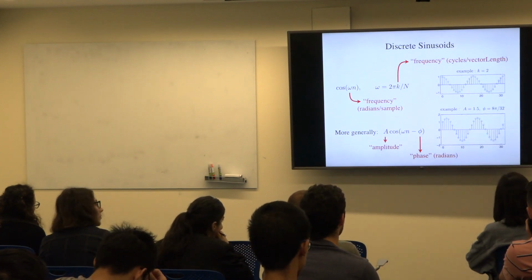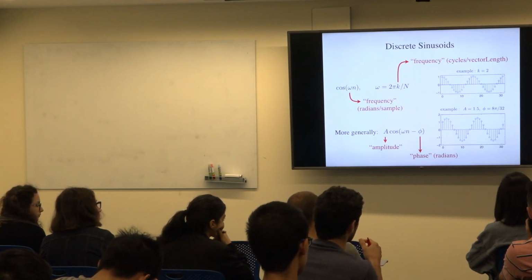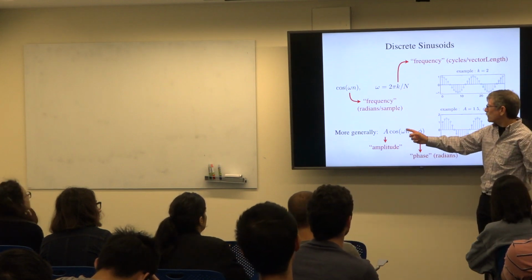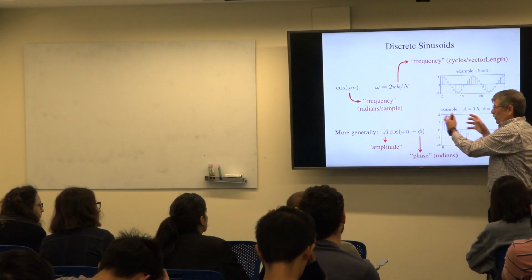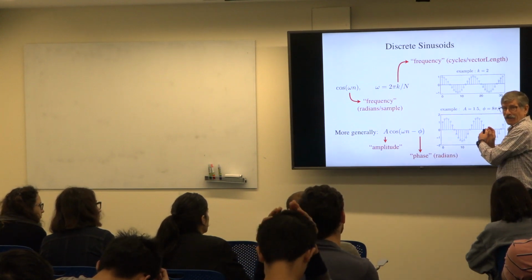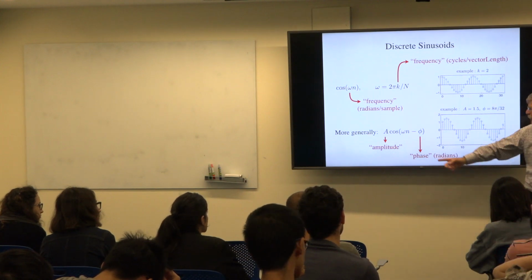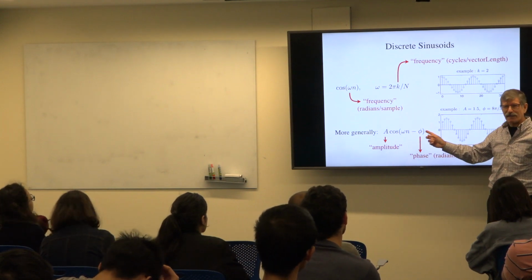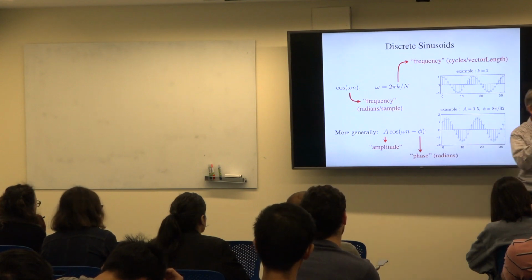If you want to shift the other way, you could have phi be negative. Phi positive means my output now is what a cosine wave would have been that long in the past. So you look in the past and put it now, which is shifting to the right. And so if you want to shift to the left, then phi will be negative. The fact that we put a minus sign here is just a convention. It's a reasonable convention, because now phi, a positive number, means phase delay, means shift to the right.